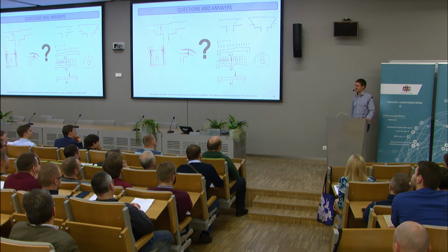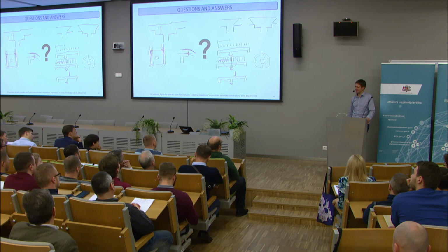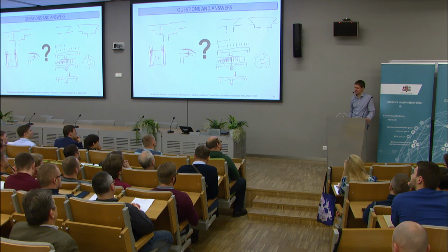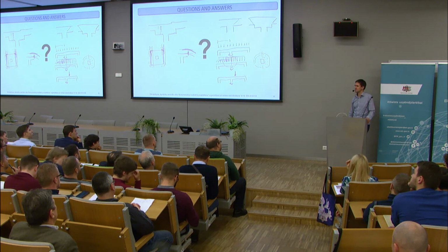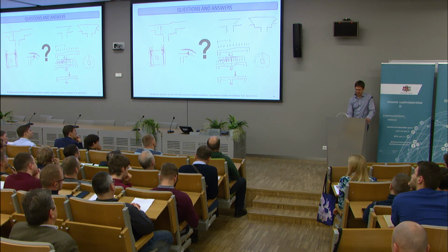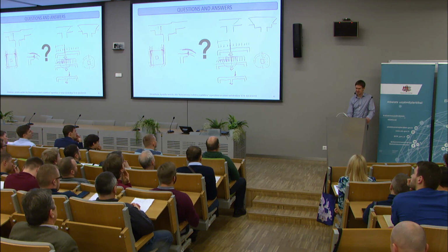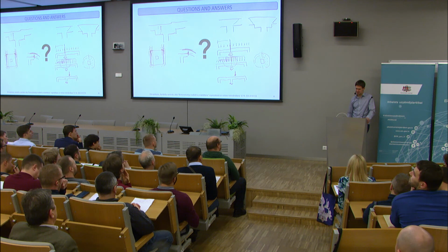It wouldn't be worth it. I mean, the amount of reinforcement saved would be lower. In this case, I would just put the larger load on the whole slab. And in this case, as I see, beta works better for cases when the spans are different, and that's the cause of different shear distribution.